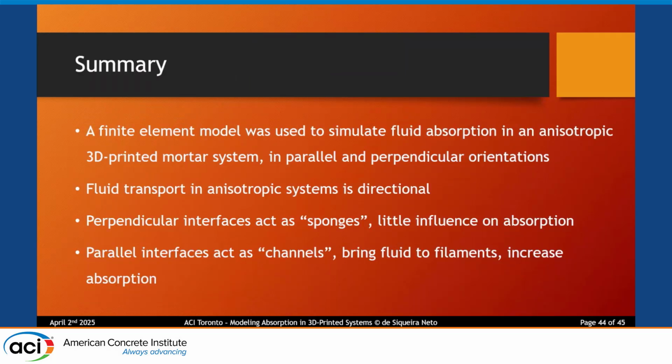So, to summarize what I'd like you to take home with you today, a finite element model was used to simulate fluid absorption in an anisotropic 3D printed mortar, and we looked at the system in parallel and perpendicular orientations relative to the main absorption direction. We have confirmed that fluid transport is directional in these cases, and we made the distinction that when the interfaces are perpendicular to the absorption direction, they act as sponges, soaking up a significant volume of fluid, but with little influence on the overall absorption in the filaments, while on the other hand, when the interfaces are parallel, they act as transport channels, bringing fluid to the filaments through lateral transport and leading to an overall increase in fluid absorption.